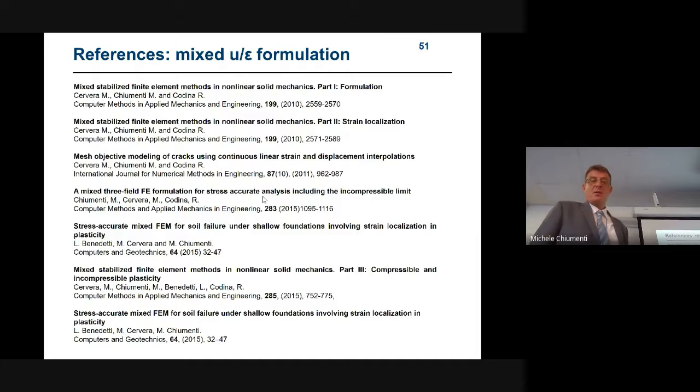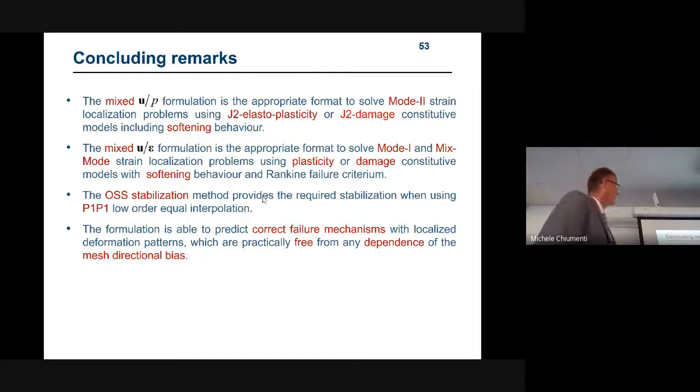Okay. So, final. I said, take care with the finite element. If you want to play only with isochoric problems in elastoplasticity, the solution is typically a mixed u-p formulation. It works very nicely and it's cheap. If you want to play with cracking, there are different alternatives in the state of the art. You can find them in the conference. Our solution is this one.